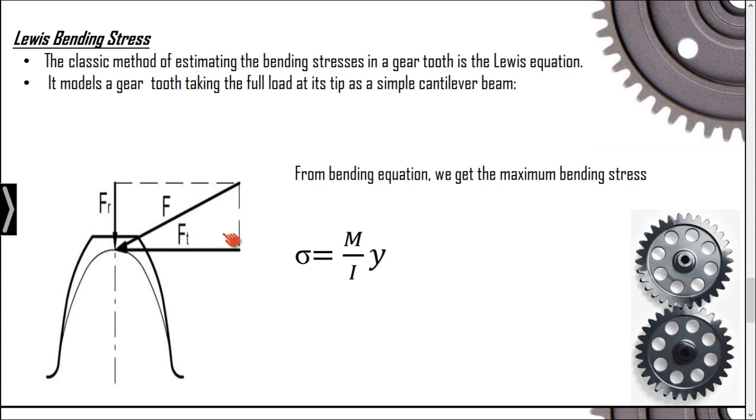And Ft, the tangential force, is the one which is going to transmit the torque or the power. So both of these two forces are very significant when we design. Mostly our entire design will be based on the power transmission, so we will be fully focusing on Ft. Ft is a very important force. It is the component of force which is transmitting the power.